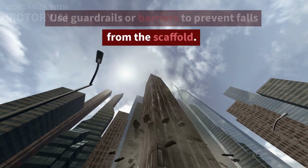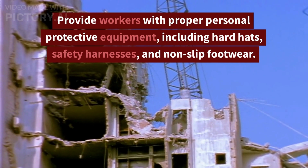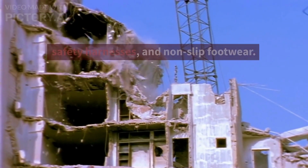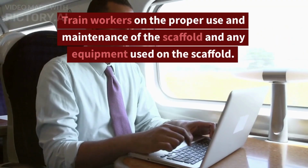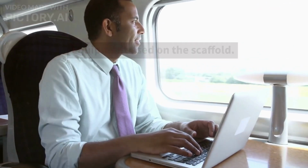Use guardrails or barriers to prevent falls from the scaffold. Provide workers with proper personal protective equipment, including hard hats, safety harnesses, and non-slip footwear. Train workers on the proper use and maintenance of the scaffold and any equipment used on the scaffold.